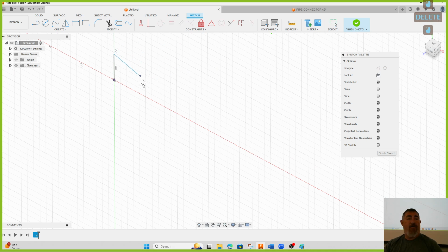But I can grab this point and drag it around. And so that's a way we test to see what's not constrained. I can see a blue line. Oh, this thing isn't constrained. How can it move? What do I need to do to lock it down? So if I draw another line from here to here, now no more white dots, because I have a closed shape, and you can see it also shaded in.